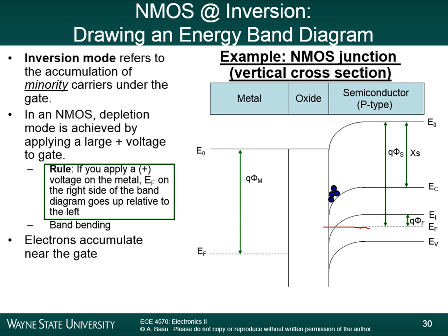And those holes, as we saw earlier, the holes in the substrate got pushed away because holes like to go up the slope, so they got depleted in this region, so the holes moved away. The electrons accumulate in this region here. This is also called the potential well. The electrons are collecting inside the potential well. This is called inversion because we've effectively switched the material at the interface from p-type to n-type. And you can see that there's a strong electric field right at the interface.